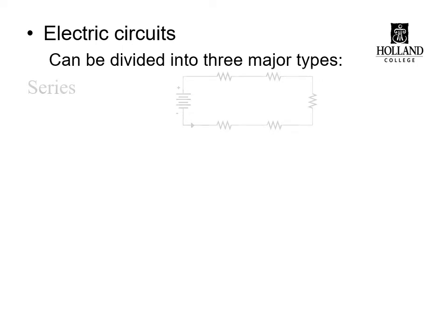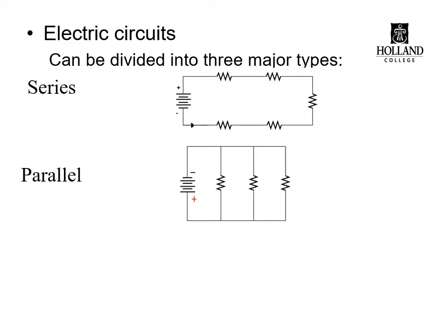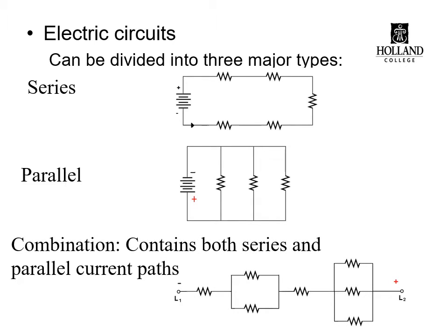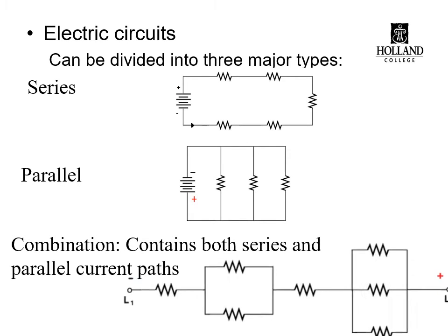So far, we've already looked at series circuits and the different principles or tenets that coincide with a series circuit. We then examined parallel circuits and did a bunch of problems for those and examined the tenets or principles around current, voltage, resistance, and power for parallel circuits. Now it's time to look at a combination circuit that has both series and parallel paths and how Ohm's law, E=IR, and P=EI can be used to solve for values for a combination circuit.